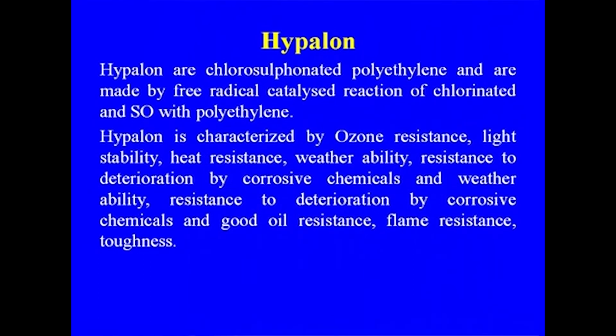So, Hypalon is characterized by ozone resistance, light stability, heat resistance, weatherability, resistance to deterioration by corrosive chemicals, good oil resistance, flame resistance and toughness. So, these are some of the important characteristics of the Hypalon.